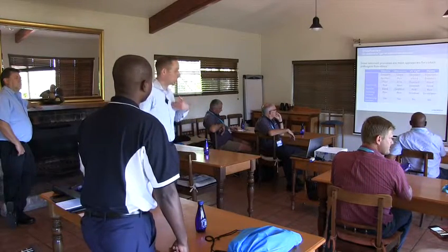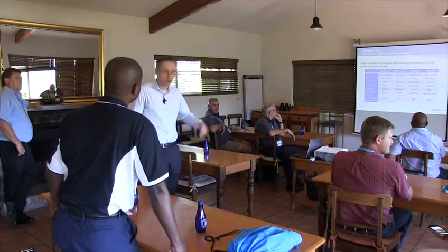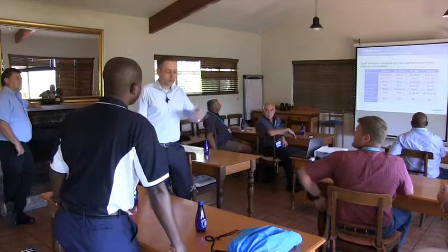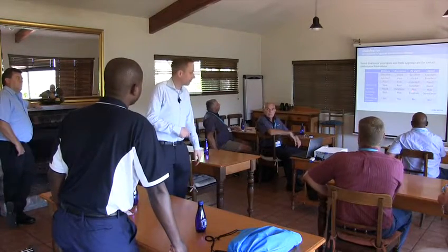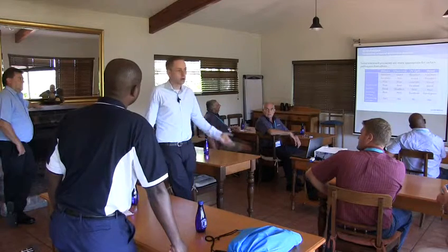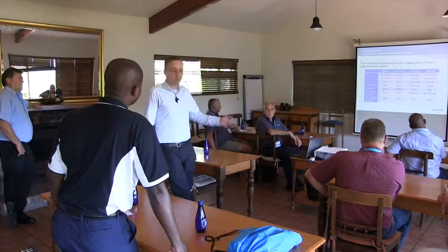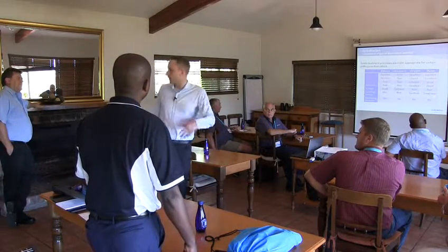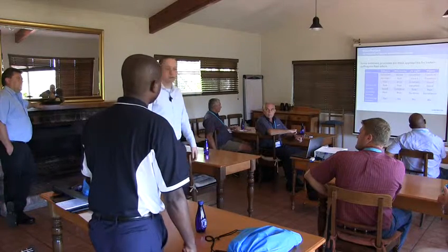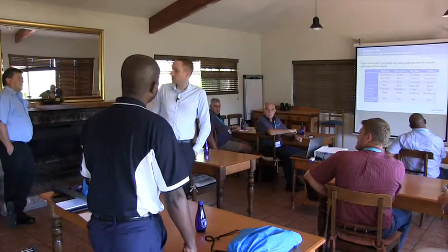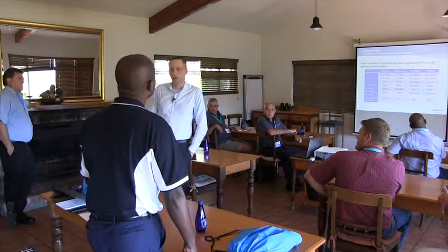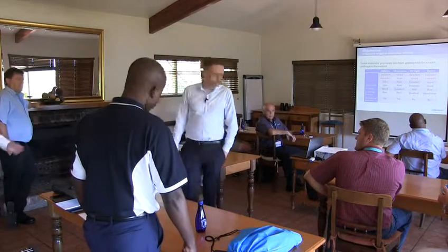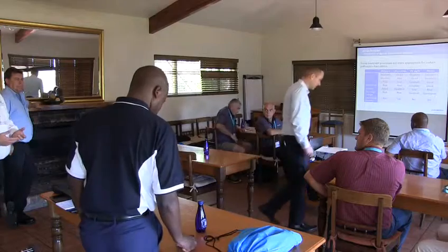Still much cheaper. I mean, I'm very interested in selling ozone too. It's not my direct department, but we have very good ozone solutions at Wedeco. But for the same application, we will be talking about maybe a few hundred watts for a UV system, maybe 1.5 kilowatts, something like that. And to get the same disinfection effect, we are talking about 25, 30, 40 kilowatts probably for ozone. You need to remember, when you're doing UV, you're generating the light wave.